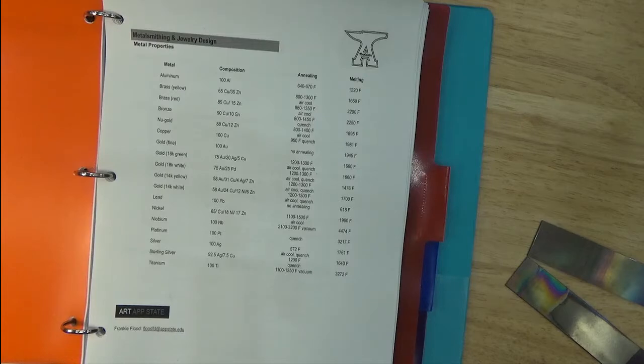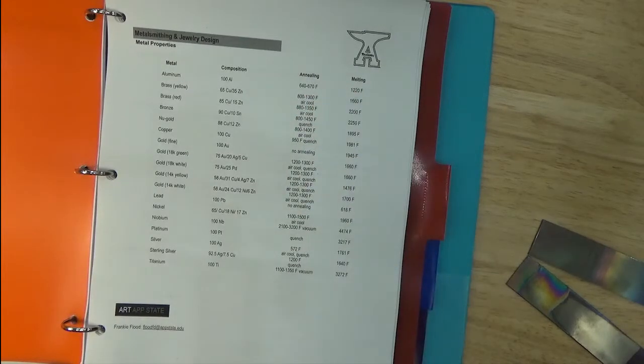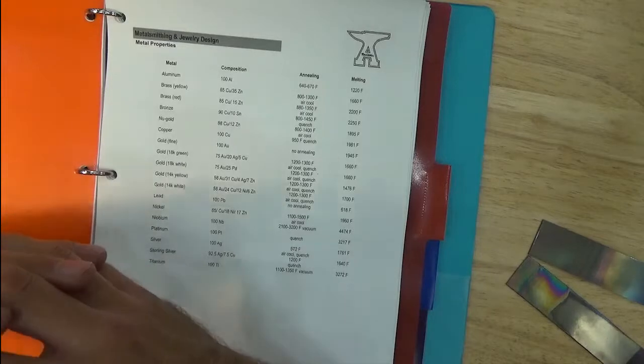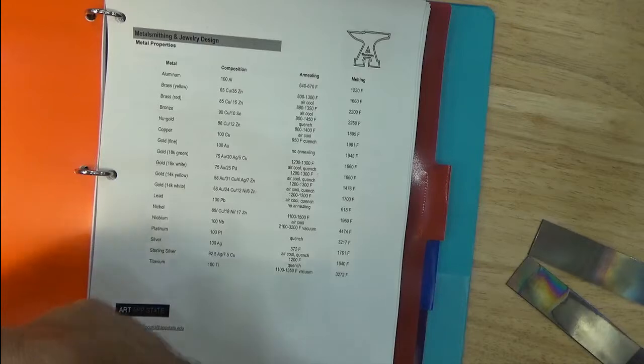The reason for that is that we're going to be doing some surface embellishment samples, and for those samples, we need to prep the metal ahead of time to accept the roller printing or the stamping that we're going to do to it. So before we impart any sort of physical stamping or forming of that metal, we need to make sure that the metal has been annealed. And annealing refers to opening up the crystalline structure of the metal so that we can then work with it.